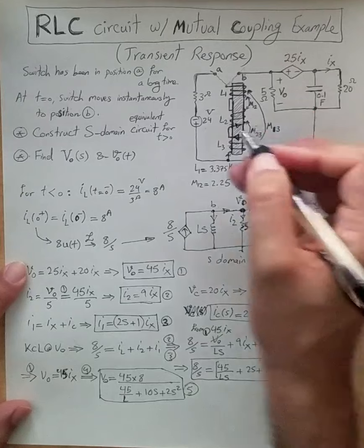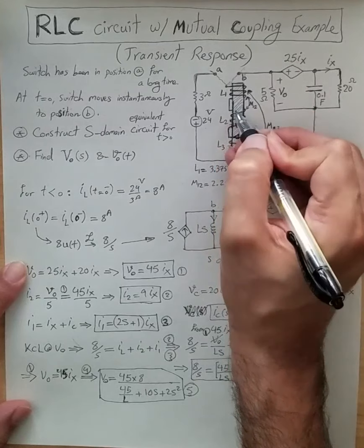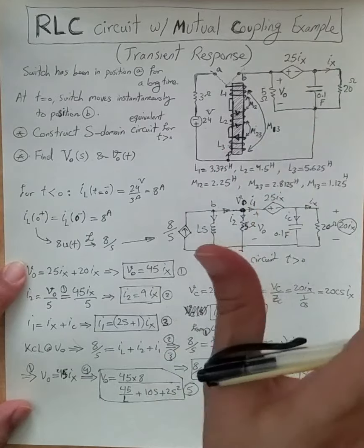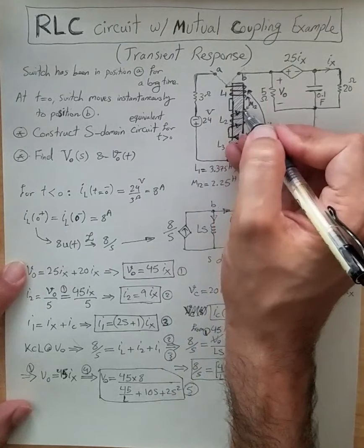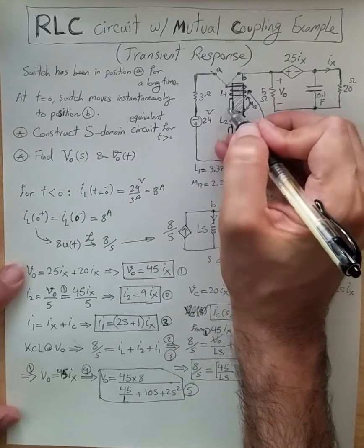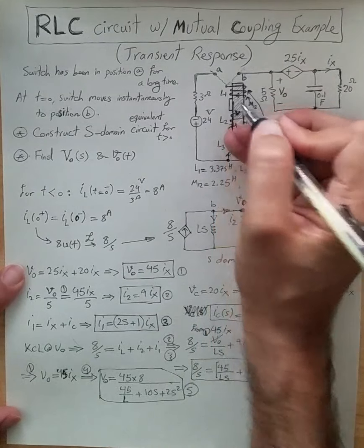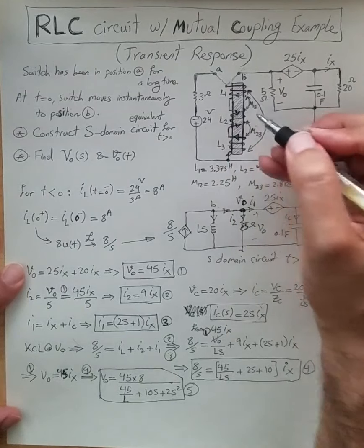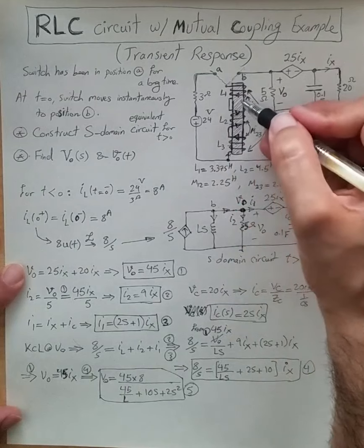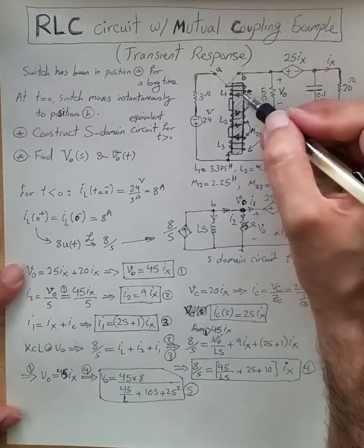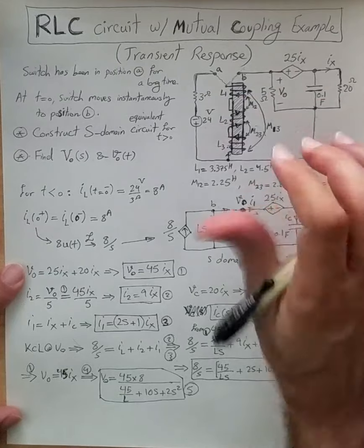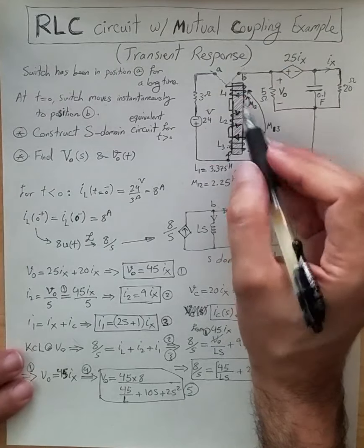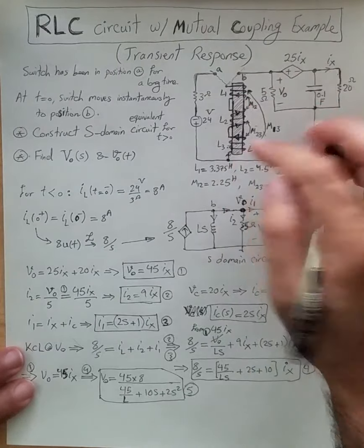would be negative. And you can see that between L2 and L1, current is going from left to right above, and then after passing below this, going again from the below to the top the other way. So you can see that L1 and L2 are counteracting each other, so the effect of mutual coupling would be a negative one. And contrary to these two cases, for M13, you can see that L1 and L3 are helping each other, because for both of them, the way that the current is flowing through the wire around the bar is the same for both, around the core.